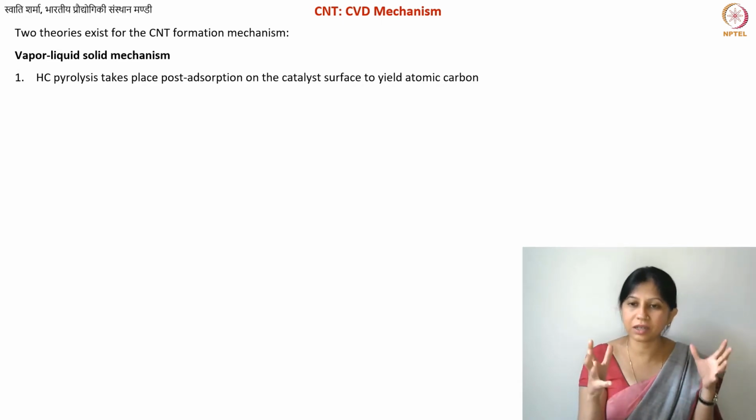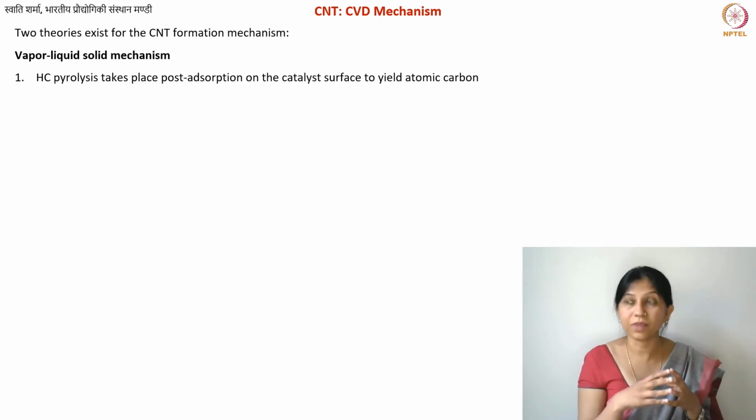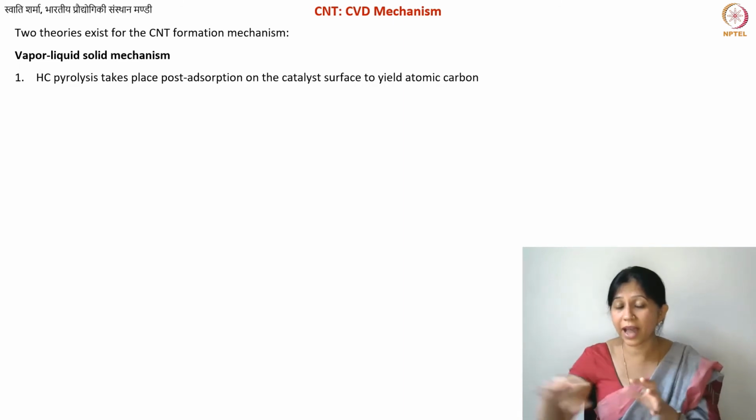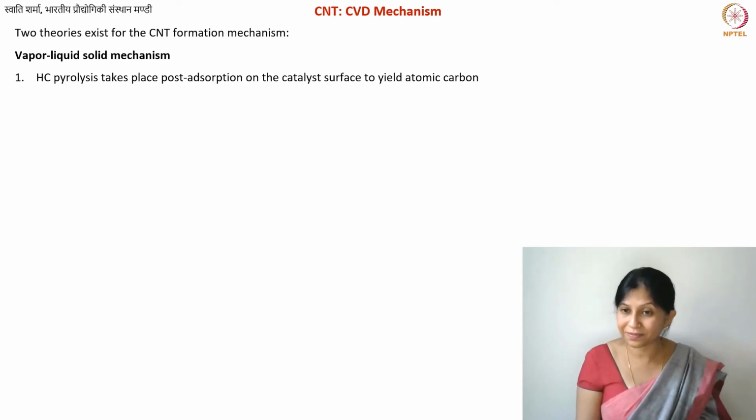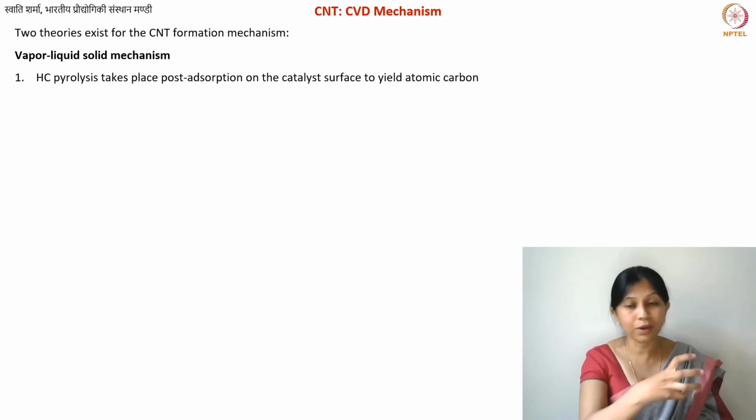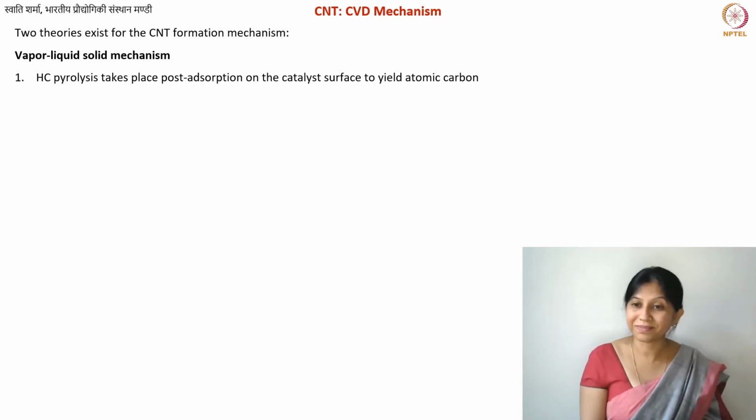So you just have a heated chamber, it needs to go above the temperature where the enthalpy of formation becomes positive for that particular hydrocarbon. And then at that temperature, what you can do is you can then flow your gas or hydrocarbon through it and then basically just observe the byproducts of the pyrolysis of the hydrocarbon itself. Okay, we also discussed this during the graphene CVD. So when you know the byproducts of your hydrocarbon pyrolysis, then you can kind of guess what is happening.